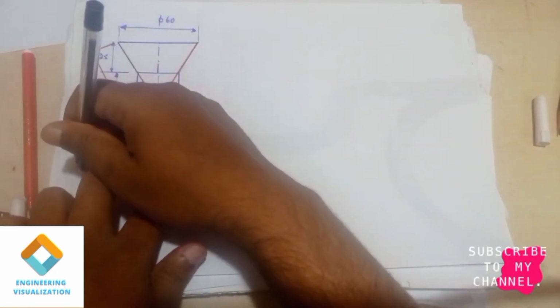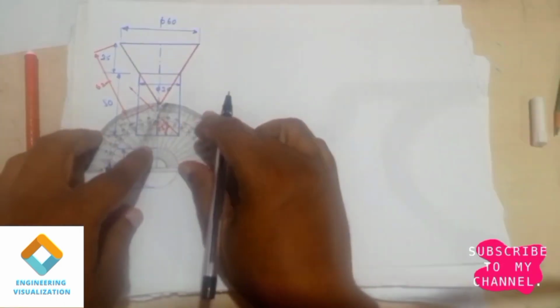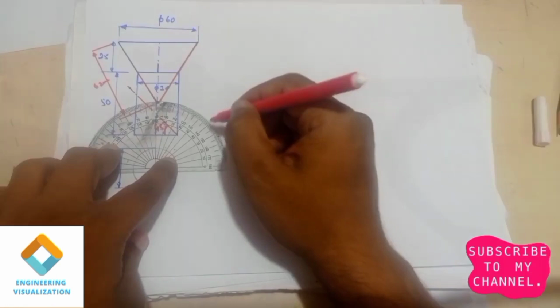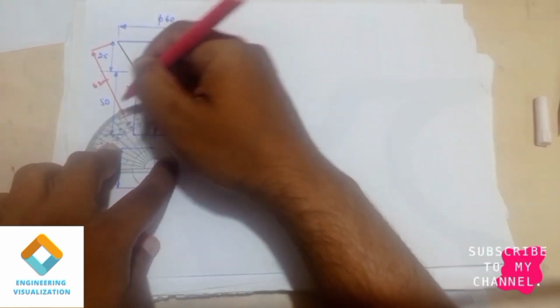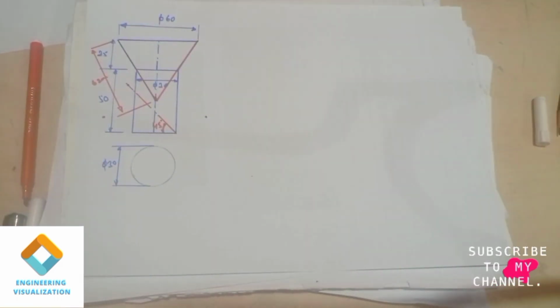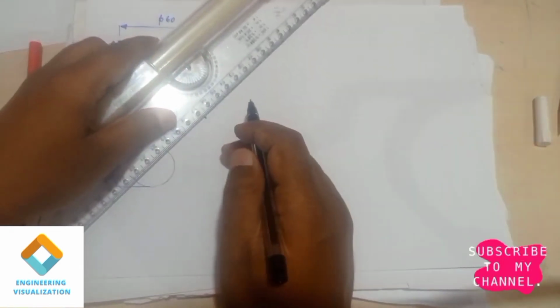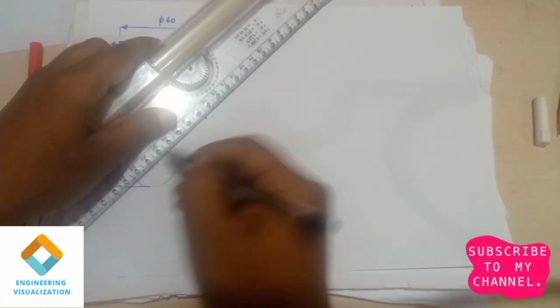I think you are not able to see the points properly, so I'll be using the sketch pen so that you can see the exact points. 45 degrees here, guys. 45 degrees, 90, 135 and 180. After marking it, you can extend using the scale, from the center point, merging it and drawing the line.